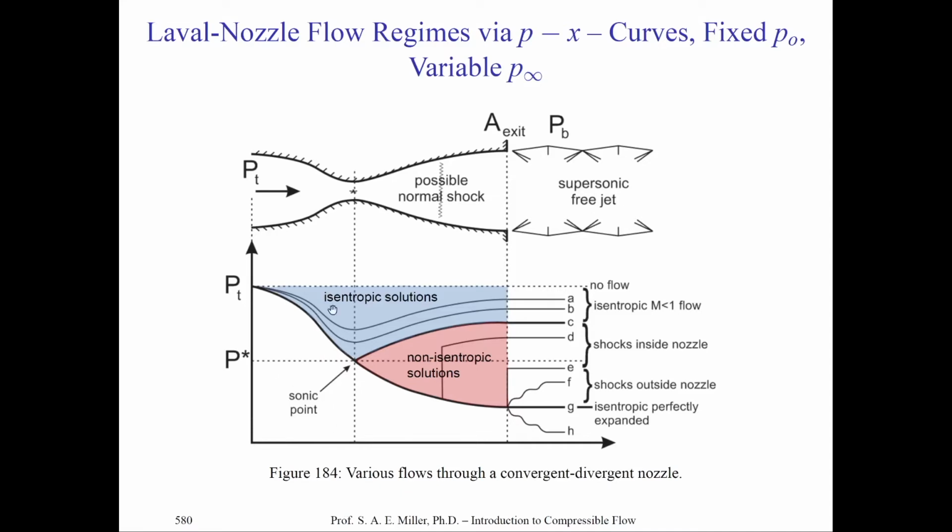You'll also see there's some particular vertical lines. This first dashed vertical line represents the location of, indeed, the throat, and the second dashed line represents the location on X of the nozzle exit. The y-axis is representative of P, of course, the pressure normalized by total pressure. So this graph is essentially what? It's P divided by PT. Indeed, it has to be that way because, of course, pressure decreases from the total pressure where the Mach number is about 0 in the plenum.